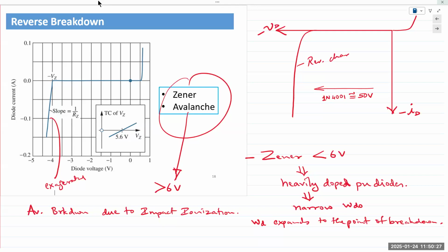Yes. So if the temperature increases, then the diode voltage would drop because there are more charge carriers. With more charge carriers, the depletion region shrinks just a little bit. So the space charge region is shrinking, the electric field drops a little bit, and the built-in junction potential drops a little bit. It's very small, in millivolts, but it's very well defined. So for every increase in temperature, the diode voltage VD would drop.